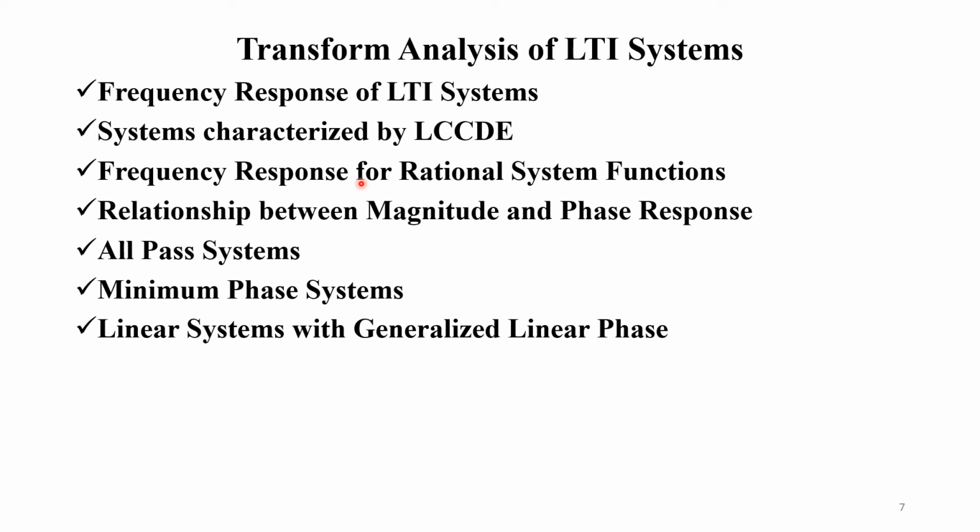So in case of a minimum phase system, the frequency response magnitude, or simply the magnitude response, specifies the phase uniquely, and the phase response specifies the magnitude to within a scaling factor.